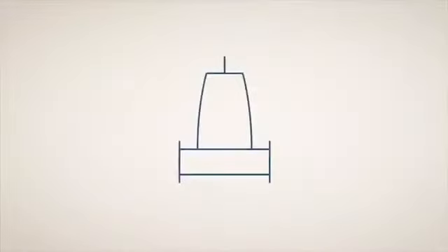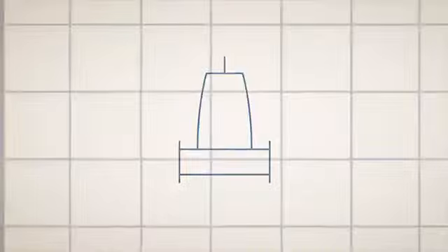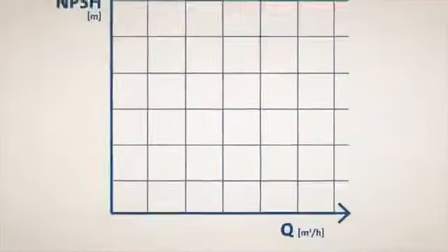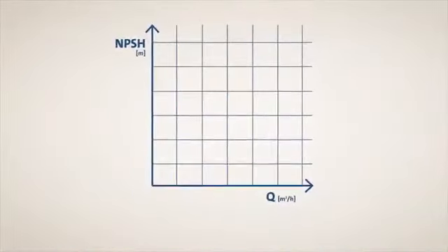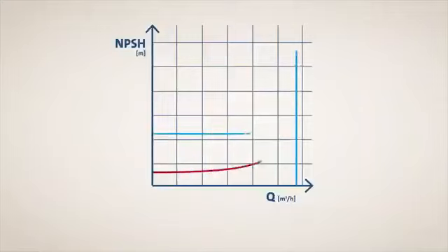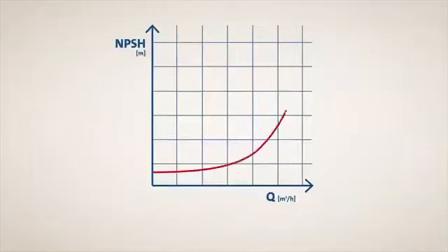Pump design can also affect what the pump performance curve will look like. There are both flat and steep pump curves. Flat curves occur when there is a small change in head, resulting in a big change in flow, as you can see here. Steep curves, on the other hand, occur when there is both a small change in head and in the flow, as shown here.